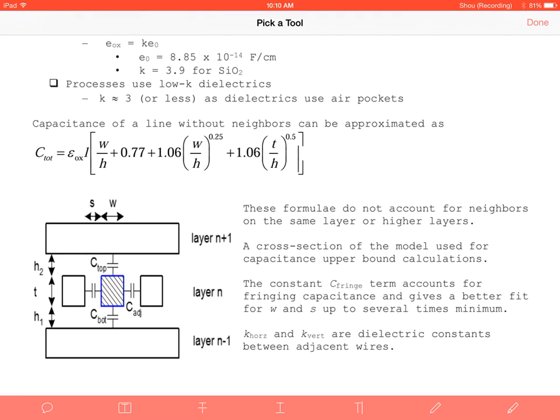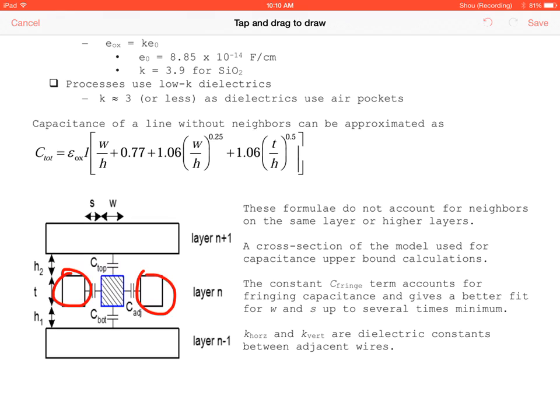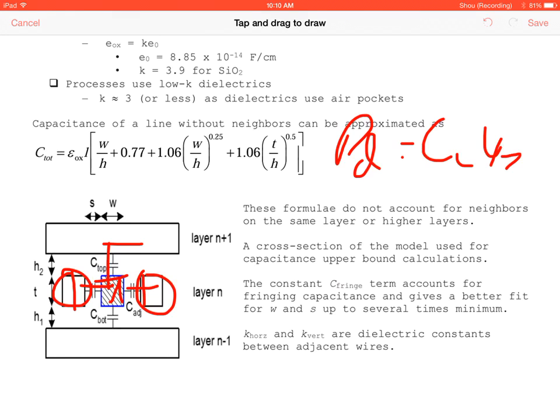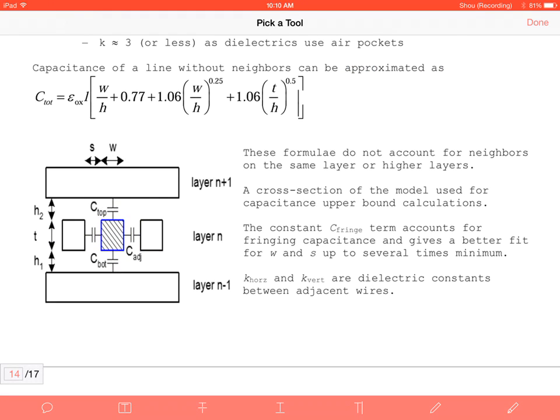So you can see as you're adding wires, the key detail here is you have some sort of capacitance, and then again switching, C L V DD squared, switching factor times frequency. So the more capacitance you have, the more power consumption you have to worry about.